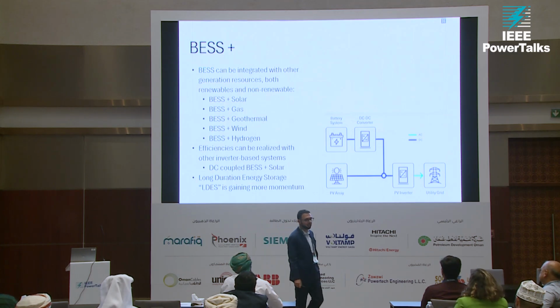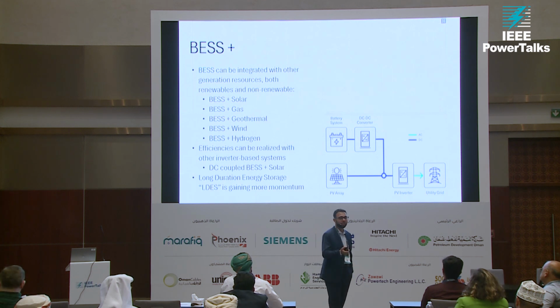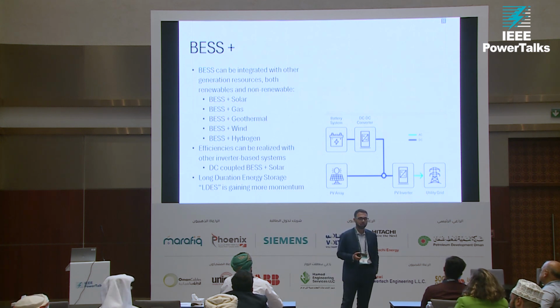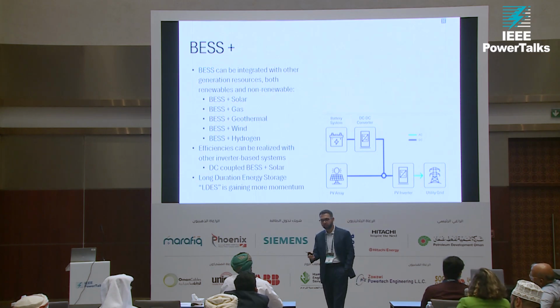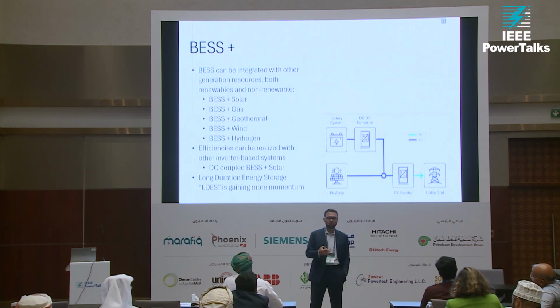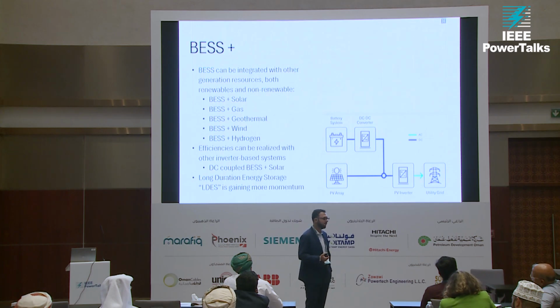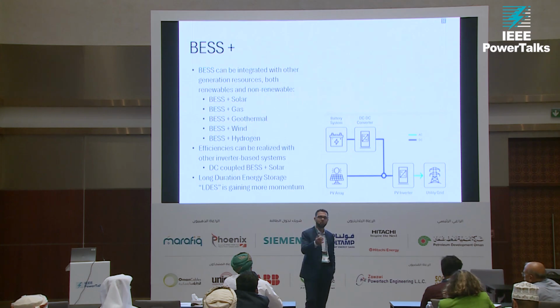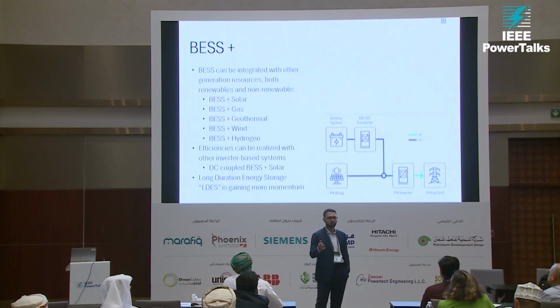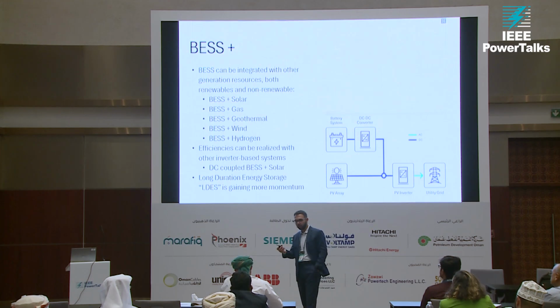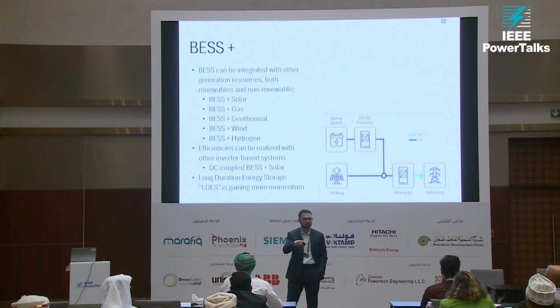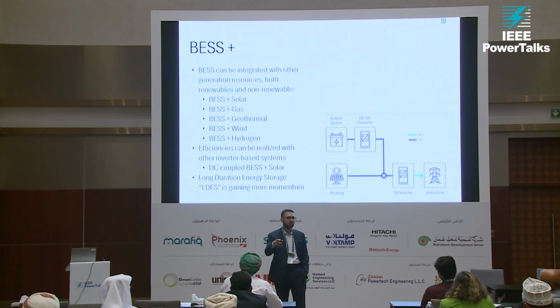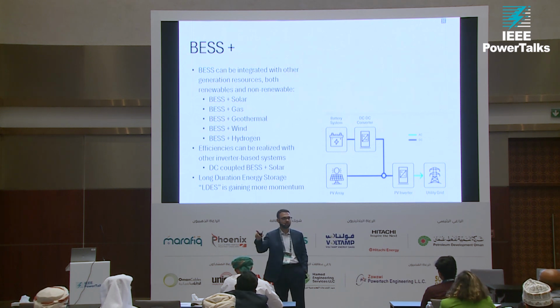Very good questions. Thank you. They're actually closer to the loads, not closer to the generation most of the time. We like those systems to be closer to the load. In terms of how we define the locations, we do full distribution load flow studies, and we have dynamic models. I've heard some of you are doing that in your grid as well. I don't think this is exclusive to North America per se, but we start virtually putting these systems in and virtually operating them before they're physically installed, and see how that improves the grid.